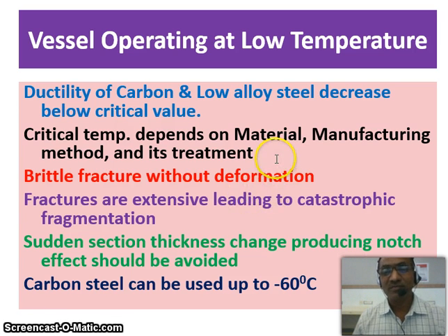When the material is subjected to a low temperature application, it fails due to brittle fracture without giving any type of deformation. These fractures are normally extensive and lead to catastrophic fragmentation of the equipment. You also should know that to avoid such conditions, sudden section thickness changes producing the notch effect in these equipments are required to be avoided.